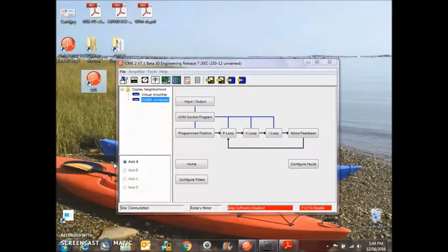And definitely if you use CANopen, there's programming software for CAN. CMO is the Windows version of CANopen programming, and CML is the C++ library for, you know, like a Linux operating system programming language. But for our needs, single axes of just move it back and forth and let it run for a test. This is a great way to test out a mechanism.